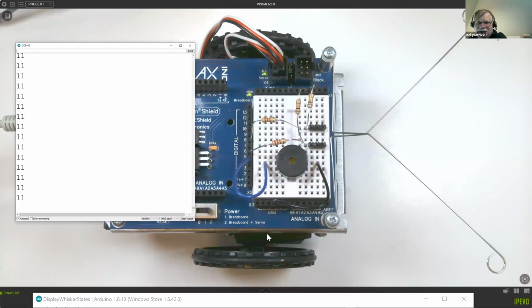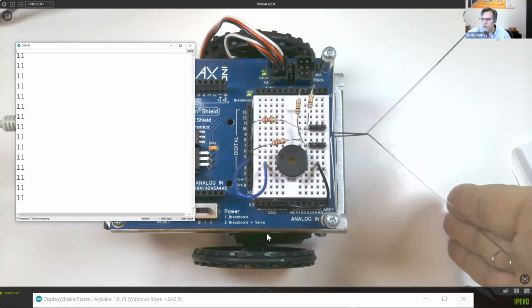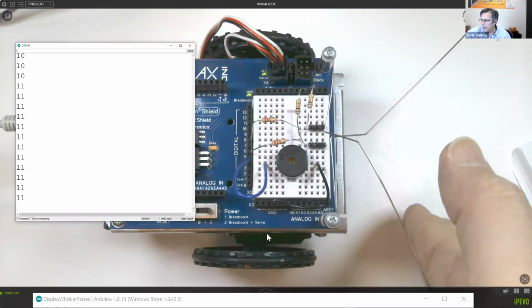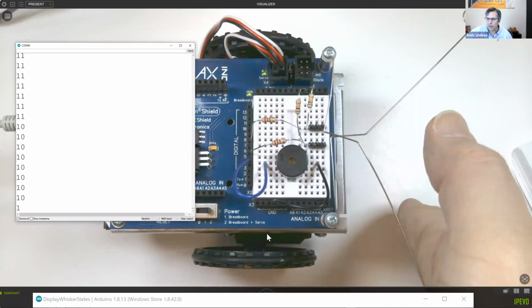The navigation? Yes. Okay. And that's on page 156. That's one we're gonna skip because it takes time to build the LEDs and we don't have quite enough time for that. So roaming with whiskers on page 158. Okay. Roaming with whiskers. For that one, you'll go ahead and load the code and then unplug the USB and then try setting it on the floor and have it run into your hand. First of all, test with your hand just to make sure that when it runs into it, it'll back up and turn away.